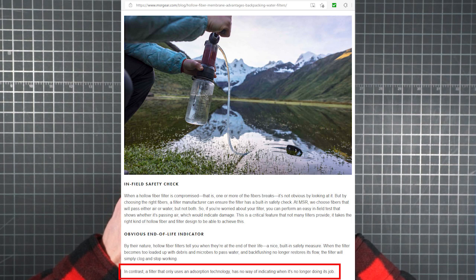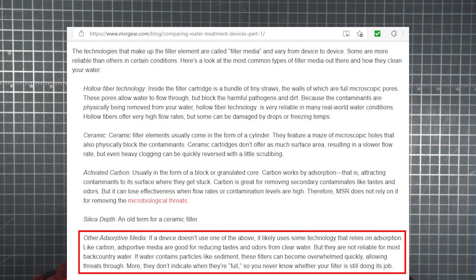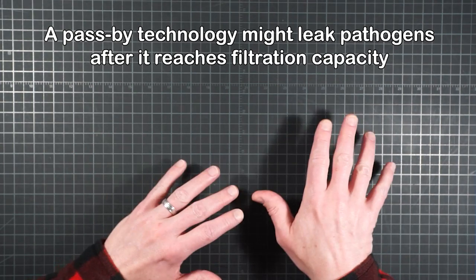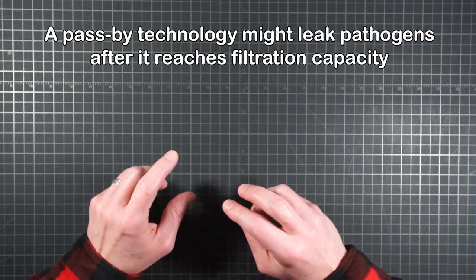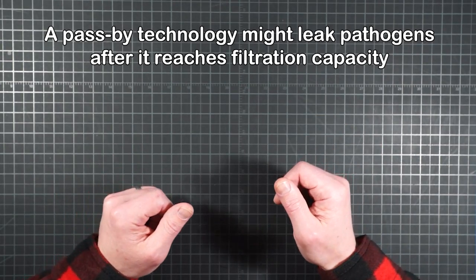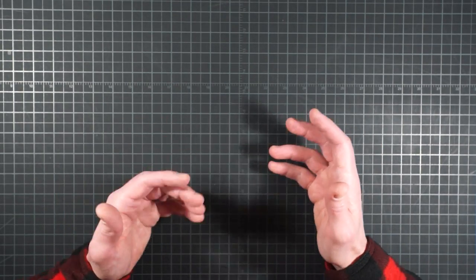In contrast, a filter that only uses an adsorption technology has no way of indicating when it's no longer doing its job. It's then suggested that when adsorption media is overwhelmed, threats can be allowed through. And that's tricky because the water you might need to filter can vary dramatically in its dirtiness, so you never know quite how much you can filter before the media is spent. But whenever your filter does suddenly cease to remove pathogens, a pass-by technology like adsorption might silently start producing unsafe water without providing you with any warning whatsoever. This is a potentially serious, even dangerous problem.